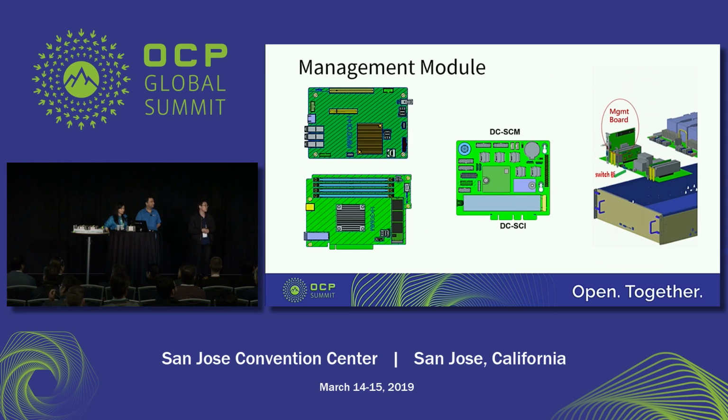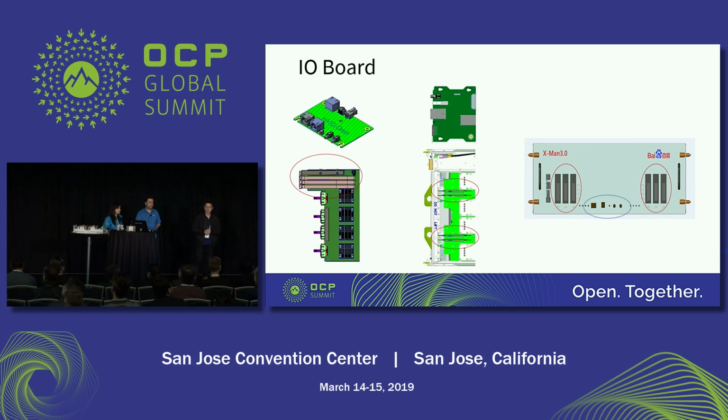And for the management, if you are deploying a large scale of servers in the data center, remote monitoring and automatic management is very important. So standardizing the management module is very important. And for the I/O board, here I/O means networking I/O, storage I/O, and also the I/O between the CPU and the accelerators. The I/O board should be as flexible as possible so that it can support different scenarios as required. And there are also some miscellaneous I/Os: the LED, the button, and the management port. So it's better to standardize these as well.